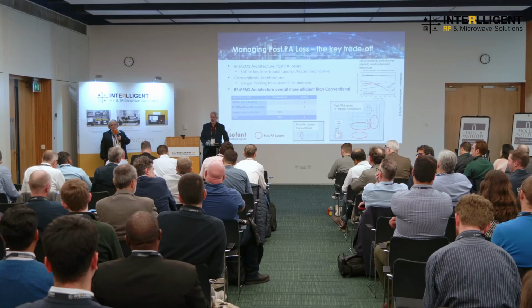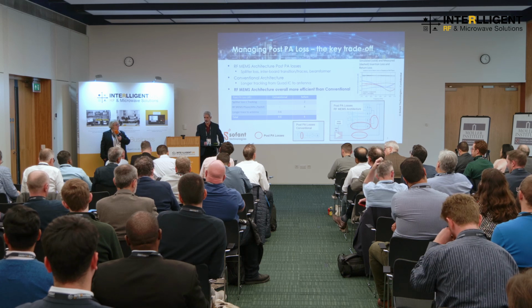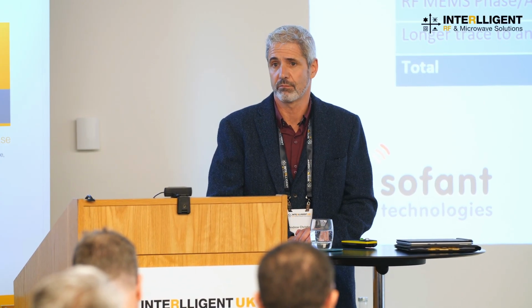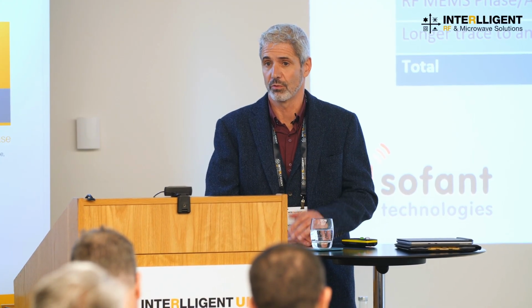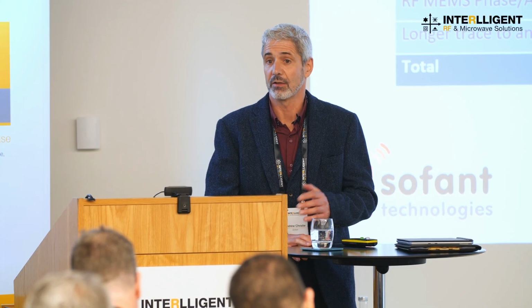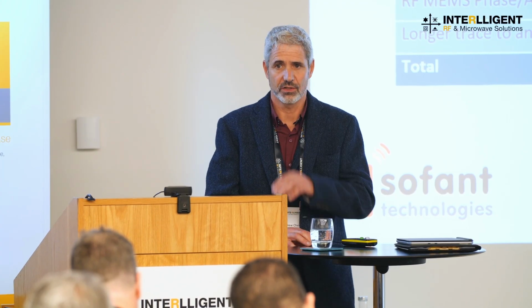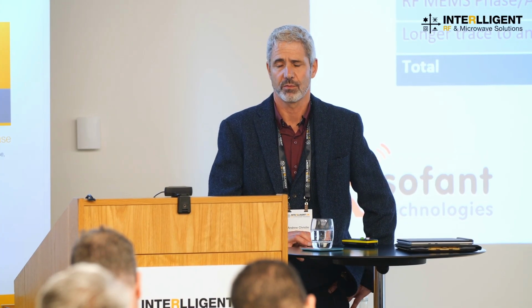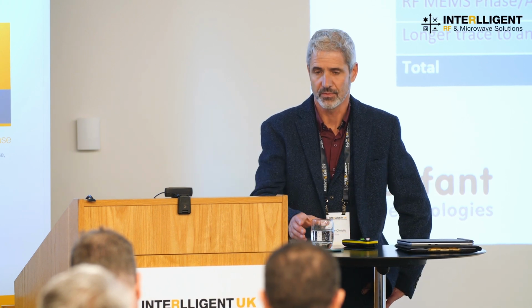We've done some price benchmarking, and we think it can be equivalent to a conventional approach in terms of cost. The GaN PA is quite small. One of the nice things about GaN, as the earlier presenters have presented, is it can have quite high current density, so you can make the die very small. So you don't pay a penalty in terms of cost. We have a less integrated solution, that's true, so there might be a small difference in assembly cost, but otherwise from a component cost comparison with conventional, it's equivalent. All right, thank you.